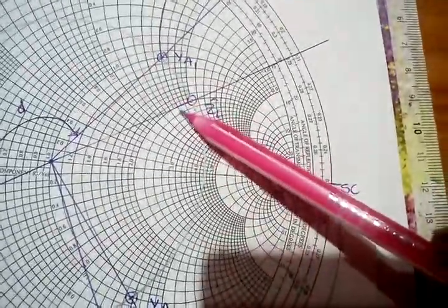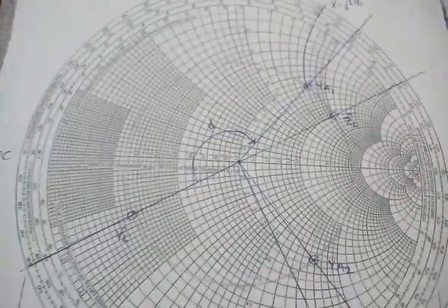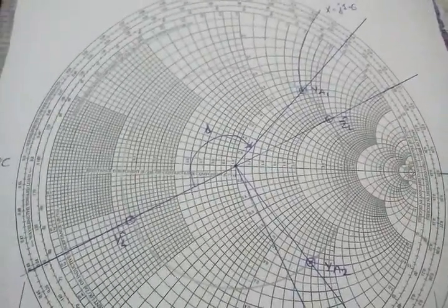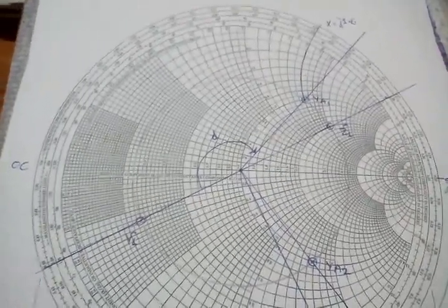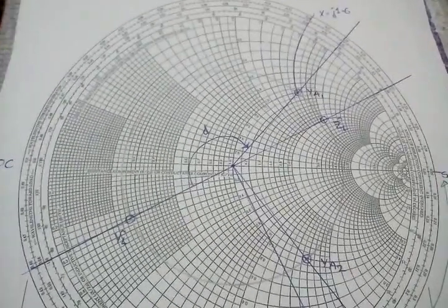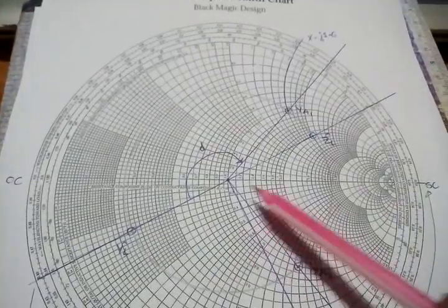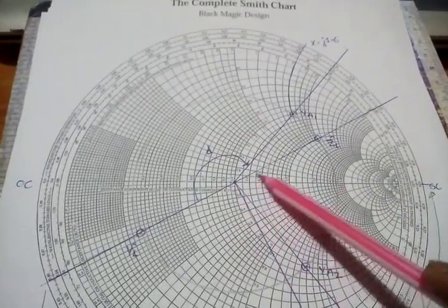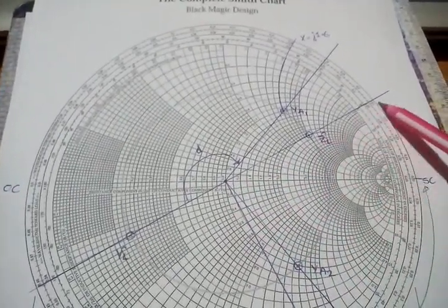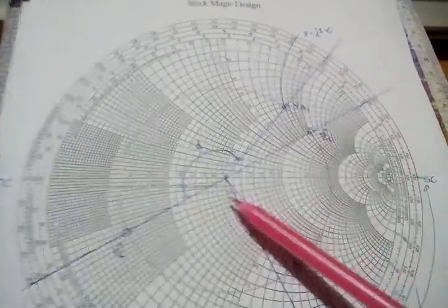Once I do that, for parallel stub, we know that it's easier to do parallel stub calculations if we have admittance. So how to draw admittance? From the center of Smith chart, draw a line across passing through the outer circle. Then take a compass,